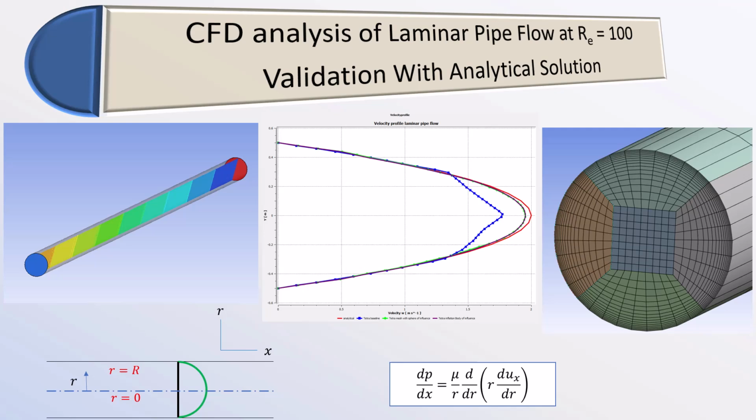But the problem is that when we are working with internal flows, the region is mostly confined with walls on all sides. So we can say that all the flow inside the domain is in the boundary layer, so we need a fine mesh. Even so, the overall solution variables are okay. I have compared the mass flow rate, pressure ratio, shear stress, skin friction coefficient, and Darcy friction factor. These values are all okay, with a very minor percentage difference.